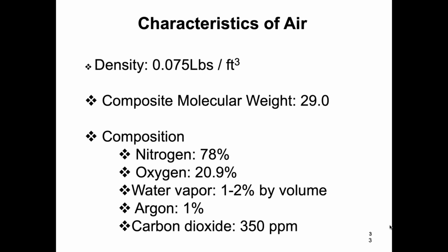When you take that full industrial ventilation course, you really take a close look at all the formulas involved in calculating all this stuff. You're interested in the density of air. That's the density of air here at sea level, in New York City. The density of air in Denver, where it's a mile high, they call it the Mile High City, at 5,000 or 6,000 feet above sea level, is different. So when you move air at the same velocity, you're doing less work because you're not moving the same amount of mass. So there are situations where you're actually interested in the density of air.